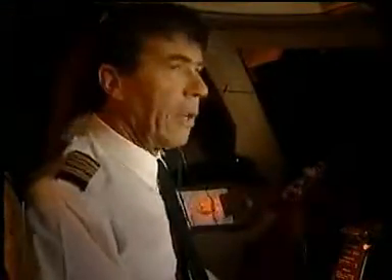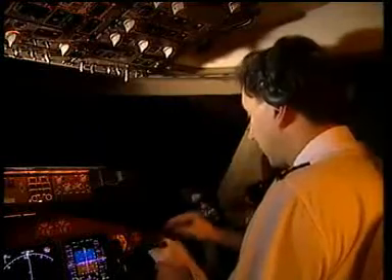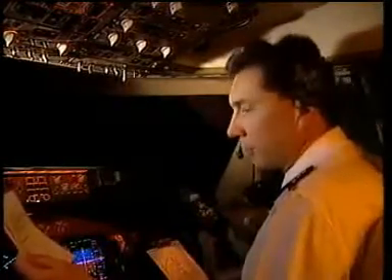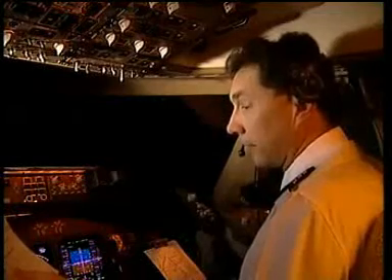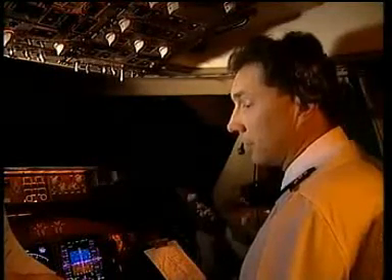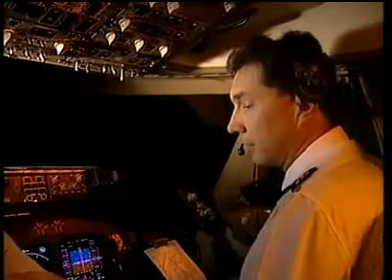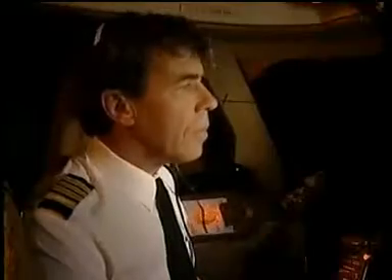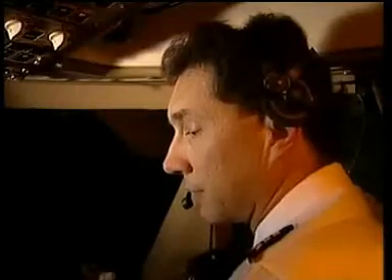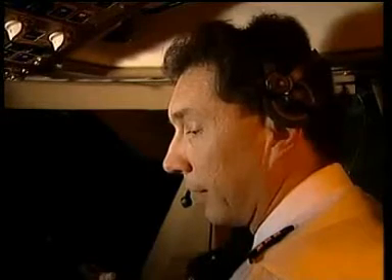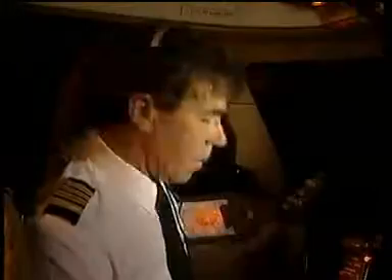Do we have the Sydney ATIS information? Yes, Captain. Sydney terminal information is Delta. Runway is 16 left and right. Wind 180 degrees at 15 knots. QNH 1007. Temperature 10. Overcast at 300 feet. Visibility 1,000 metres. Showers in area. Independent parallel approaches in progress. Expect ILS PRM approach. Independent departures in progress. Thanks. Handing over, I'll brief the approach.